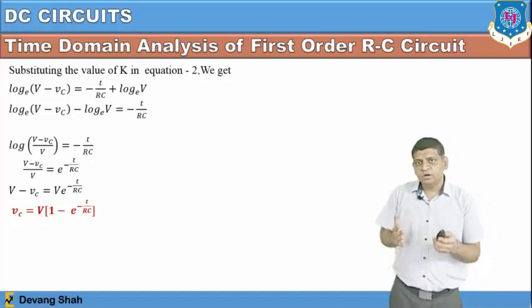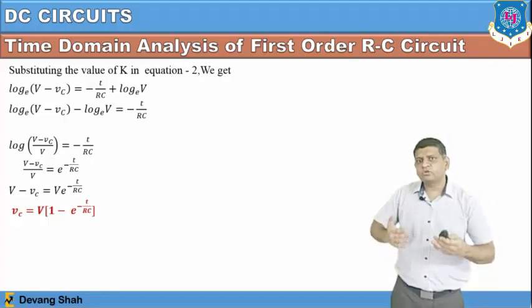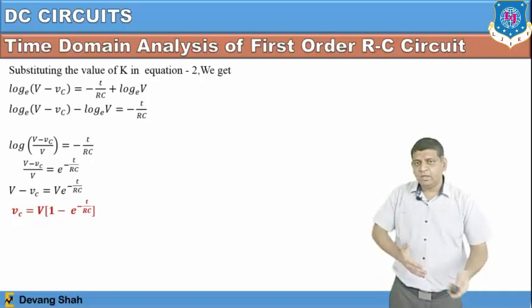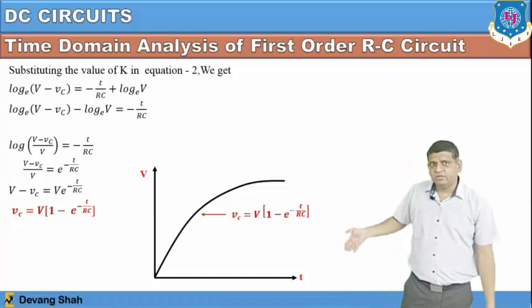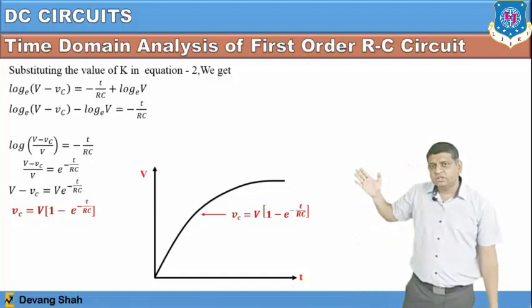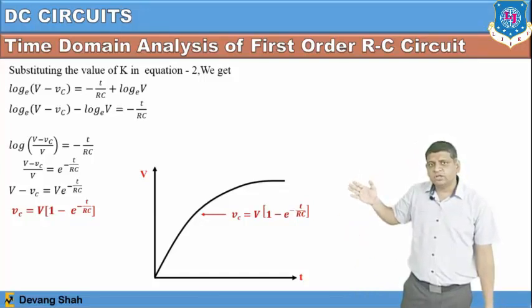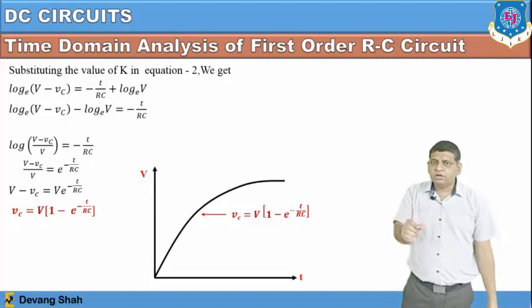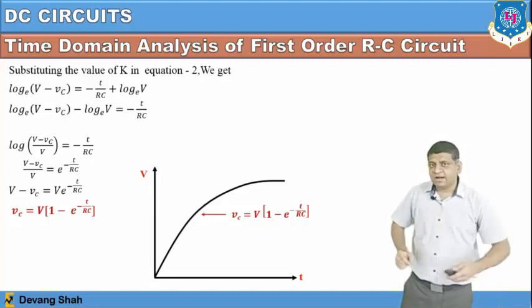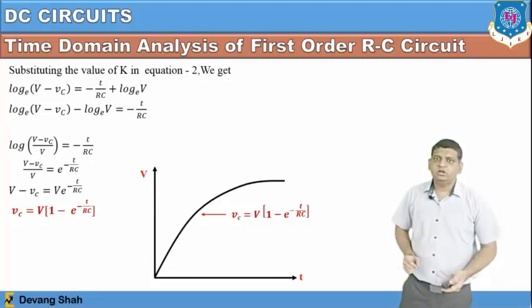So once you find the voltage drop across the capacitor with respect to time and plot it on a graph, you can see this kind of graph, where the charging voltage across the capacitor shows the exponential shape, and that represents the term V in bracket 1 minus e raised to minus t by RC, where RC I define as the time constant.